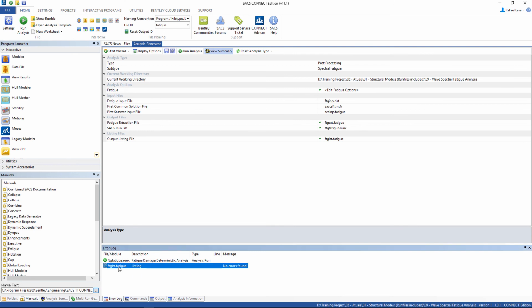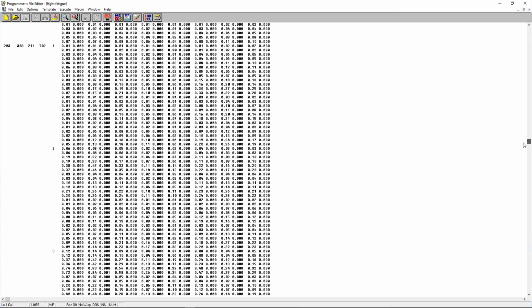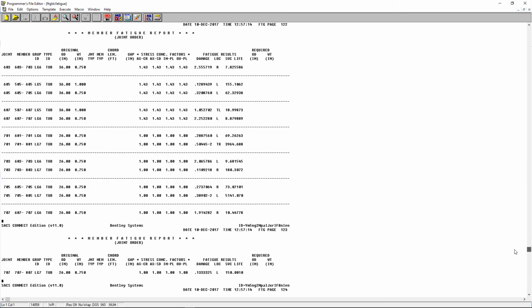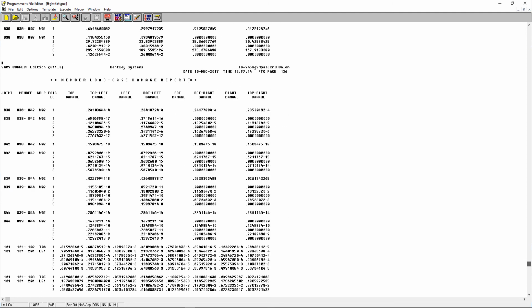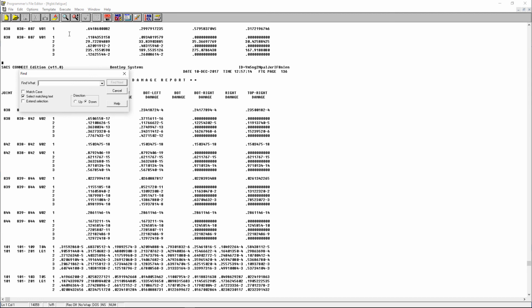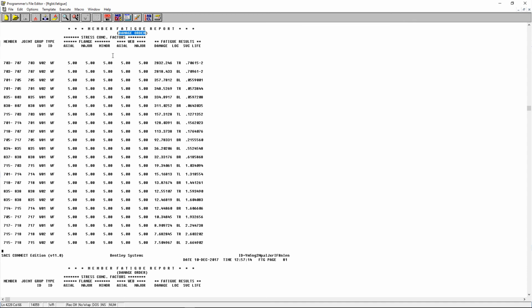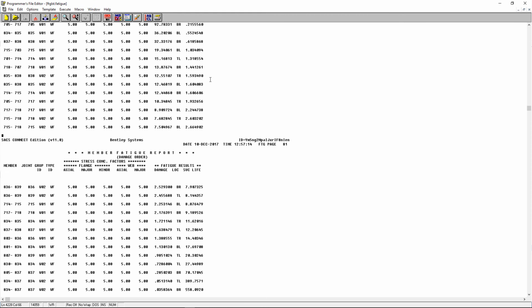Let's go to the results. Scroll down until you find the member fatigue report in the damage order. Or you can just search for damage order. Here is your report, so you can check for the results right here.